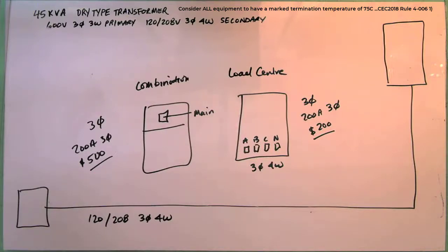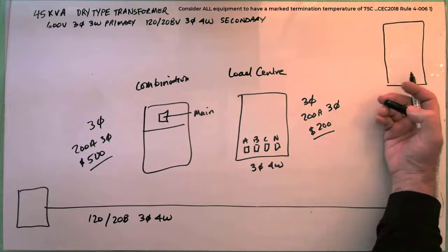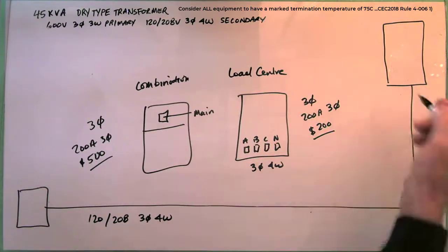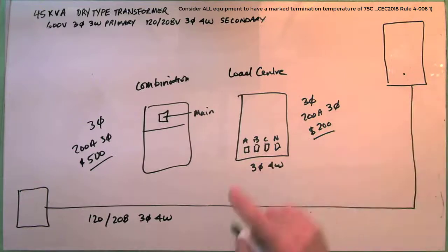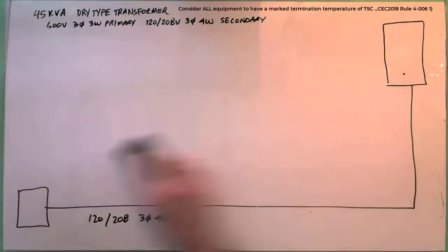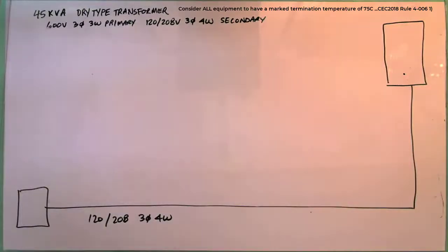In case something were to happen, let's say the electrical room was in the pizzeria, and the pizza place is open late, till 3 or 4 in the morning. The bank opens at 8, and if there's an issue, they can't get to the electrical room because a fuse is blown. That's why they want a combination panel here, so the breaker would trip here before it got to the electrical room. So there's a lot of learning. Learning is like getting defects. Hopefully it doesn't cost you too much.